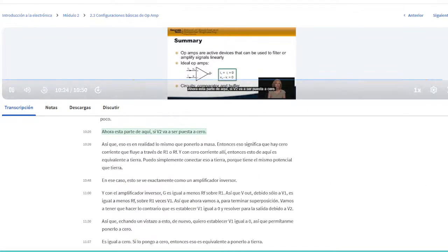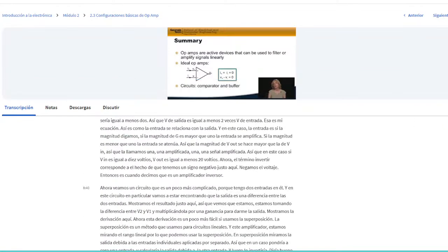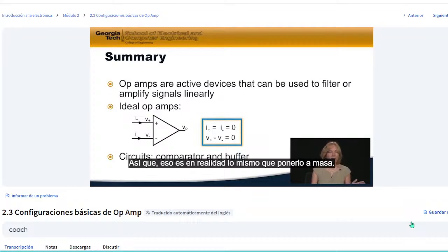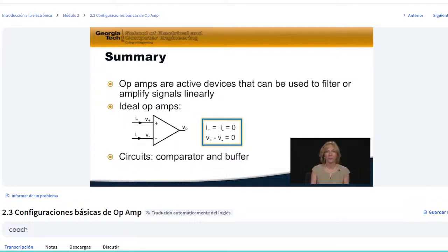looking at sensors and we want to amplify the sensors, or we want to compare two sensor readings or do some processing like that. And the other time that it's useful is the output of, say, something like a microcontroller, where we want to do something with the output before we're putting it in. We want to amplify it, for example, before we're putting it into a motor or some other device that we're trying to drive.